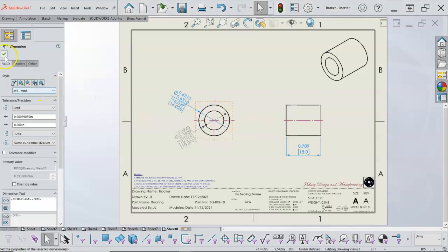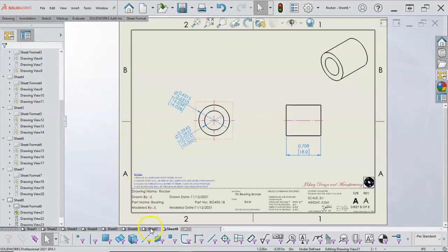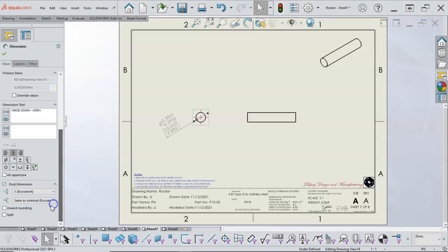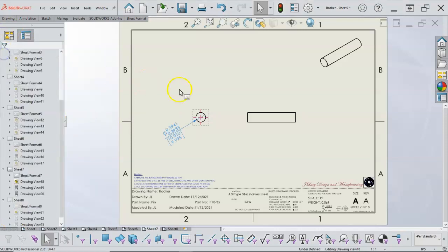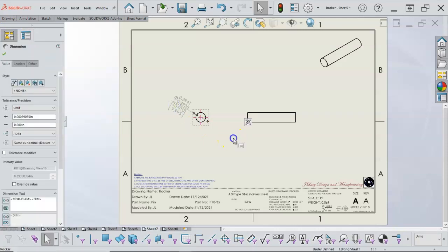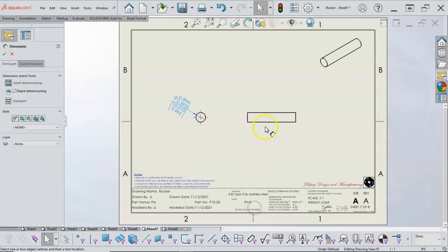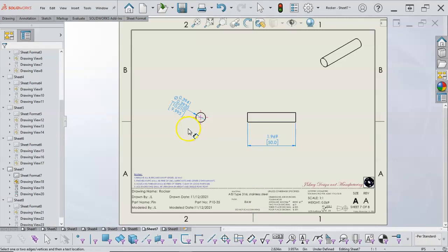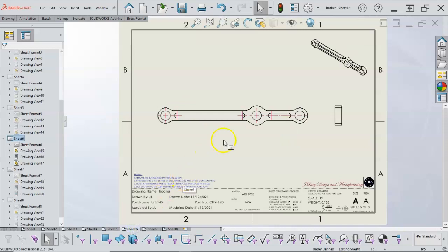And then it should show up in the list, so that when I come over to this one and I pick it, except for the split, that's pretty good. I'll bring that over where it's a little more readable. Smart dimension and the overall length. And that looks okay. I think the split on the diameter is probably a little helpful. So right now we're at the 50 millimeter, and I'll need to determine the notes for that.